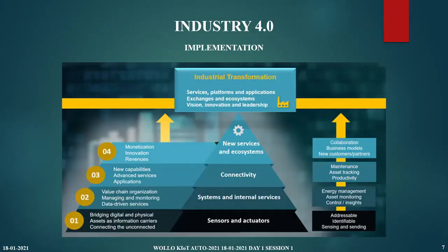Suppose some issue happens in paint, and the paint line stops. Casting, machining, and the furnace keep on running, but it cannot go to paint. There will be a blockade. So when one system is shut down completely, the other systems should know that after that particular cycle is over, they have to switch off until the system is clear and you have a green signal to go ahead. So this is why connectivity plays a major role.